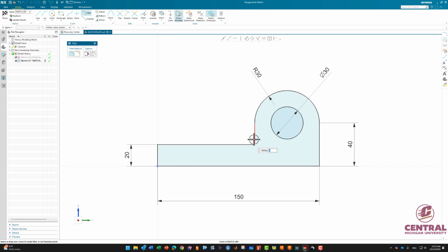So pick those two lines. Then it will add that size of 4 radius fillet automatically for you. So click, click. There we go. You added it. And click, click. But you notice that for the same size of fillet you added, it is not actually adding a dimension. But later we'll learn that NX already figured out your intention. So instead of having one more dimension, you added a constraint, an equal radius constraint already integrated. So there's some AI stuff going on in the sketches.